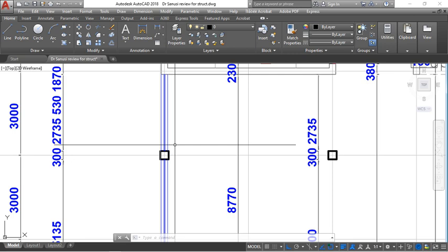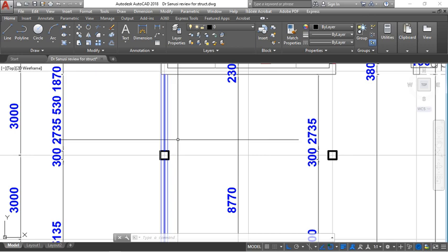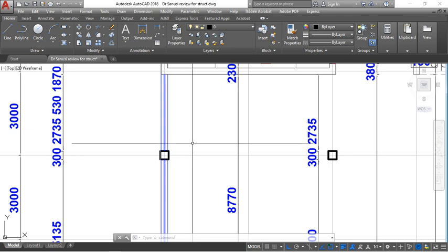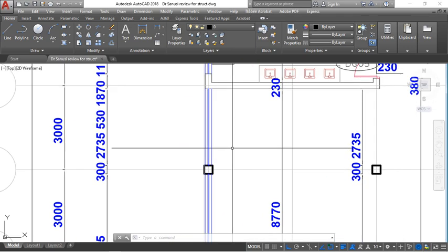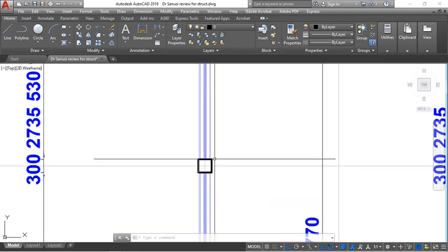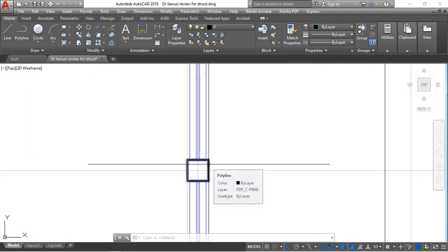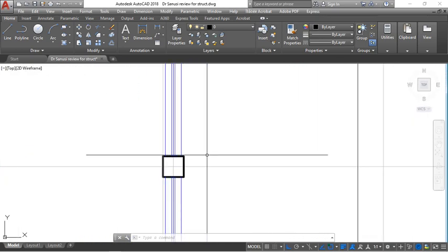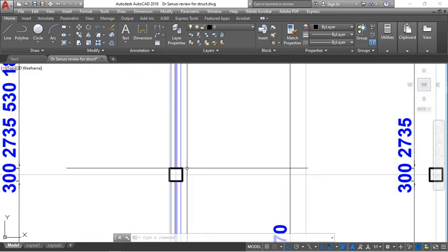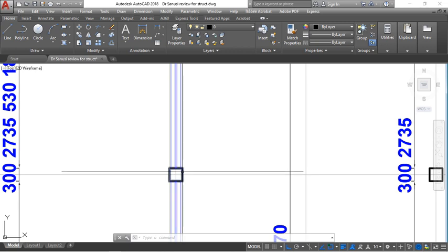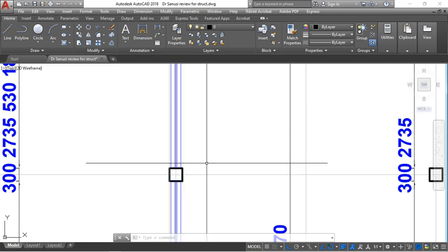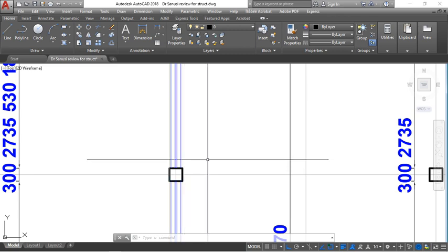So whether you like it or not, even if you are doing 150, like I said, if it is a place like Ikorodu, Songo, places with very good and very strong laterite, Abuja, very strong, then 100, 150, you can still get away. But below that, however strong your soil is, it is still subject to movement in a way, because whether you like it or not, there's seasonal change. So there will be times where water will be part of your structure, and times where water will dry as the season changes. So there's bound to be little movement, there's bound to be shrinkage at some point.